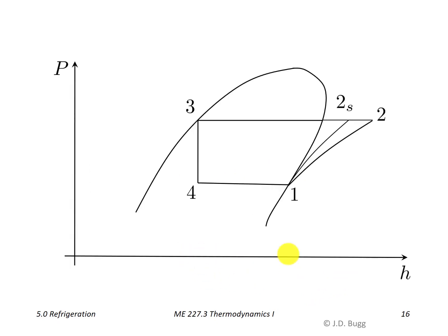Next thing I want to look at is the 2 temperatures that this system is operating between. So this is just a repeat of our pH diagram. We know that is TH and this is TC. Now everything that's being plotted here is the properties of the refrigerant or the working fluid as it goes around this cycle. So we're plotting properties of that substance on pH coordinates.